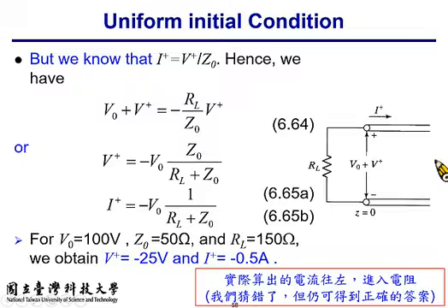And if you look at the physics of this configuration, you know that initially, before connecting to the load resistor, this transmission line is a charged-up capacitor. And when t is greater than 0, we connect a resistor to the left end, RL. So what happens? The capacitor starts to discharge energy into the resistor. So the current flow is actually going to the left, but that's okay. We can still determine the current as I plus because its effect is propagating from left to right.